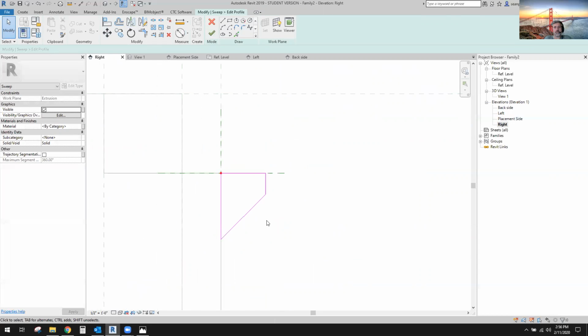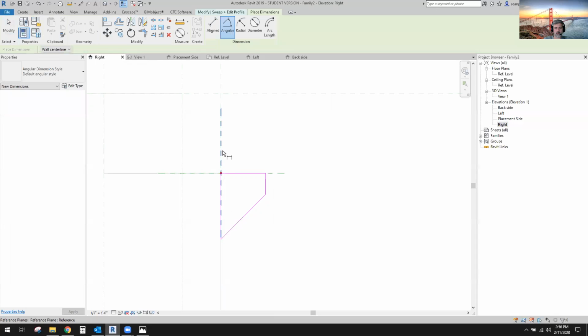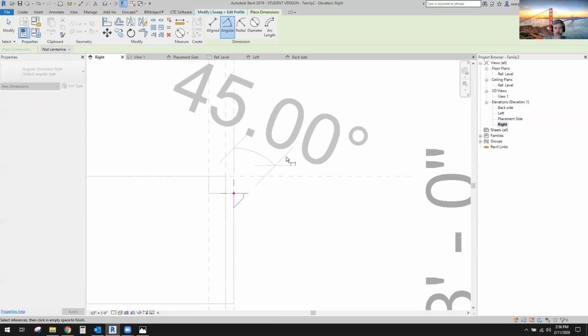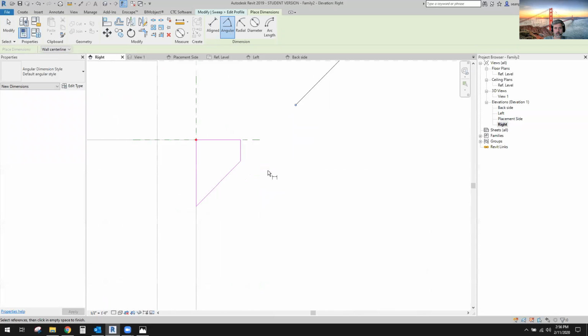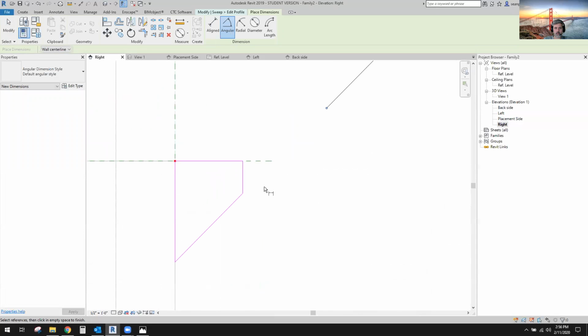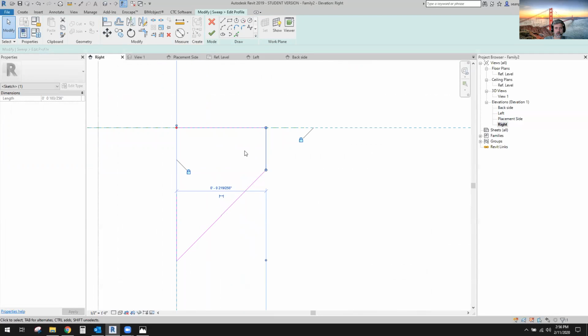So it'll stay like this no matter what you do, but chances are pretty strong that you probably want to lock it down with some dimensions if you can. So put it to a reference plane to that guy that it should always be 45 degrees and lock that guy down. And then I would let this piece probably flex. Maybe the height of it's too deep. It says it's whatever this number is, so let's give it a real number here. How about half an inch?